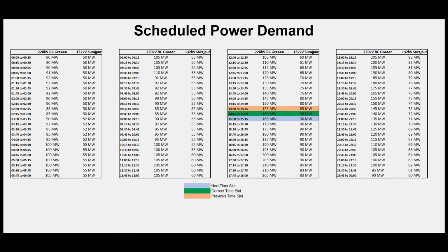As can be seen here, the ETAP iDLS system continuously compares the power scheduled to be drawn from the grid and the actual power demand at each of the transmission substations. Short-term load forecasting is used to forecast the power demand for the next few days at 15-minute intervals, and a 24-hour contract may be made between the distribution company and the grid operator specifying the maximum amount of power that can be drawn in each 15-minute interval.